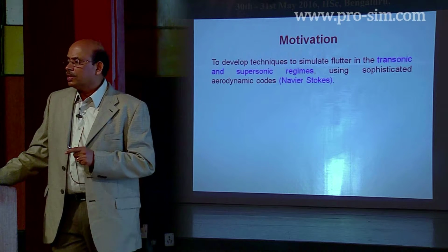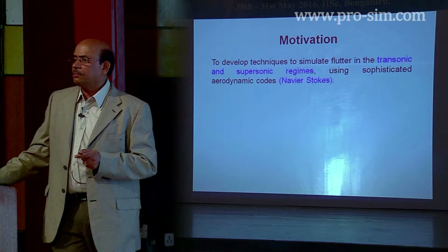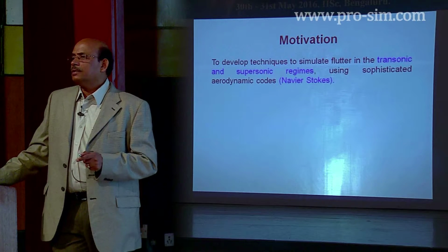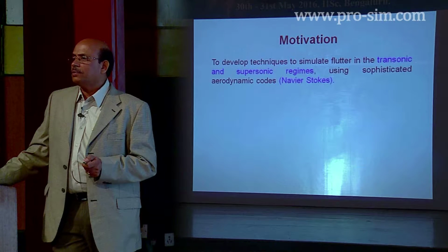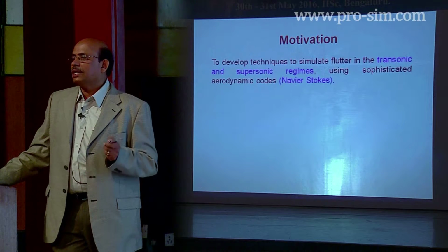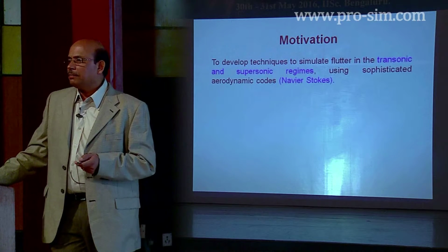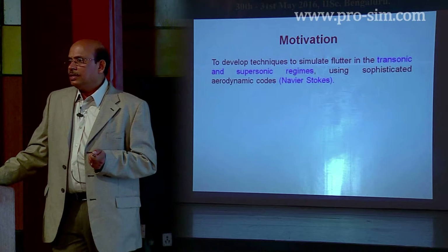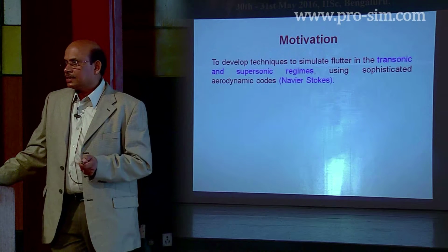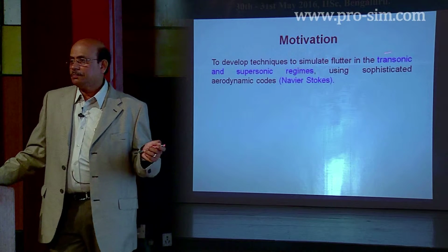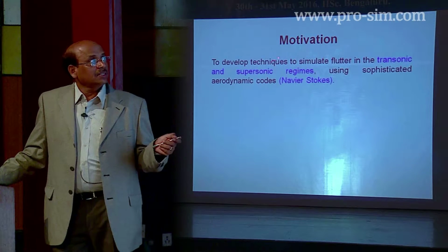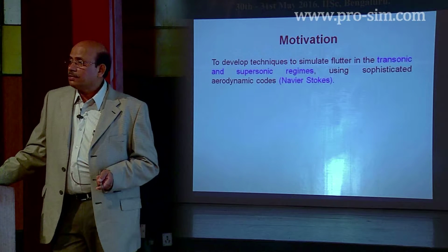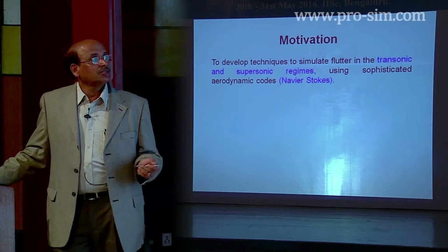The aerodynamic models and the solution techniques available there are all good for subsonic and supersonic regimes. But there are no effective methods available for the transonic regime, where we encounter really nonlinear aerodynamic phenomena. Then we also encounter what is known as the transonic dip and so on. In order to predict such characteristics, we started looking at these methods. So basically, we started developing these time domain techniques for computing the flutter speeds in the transonic and supersonic regimes.